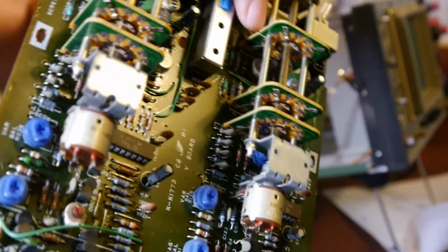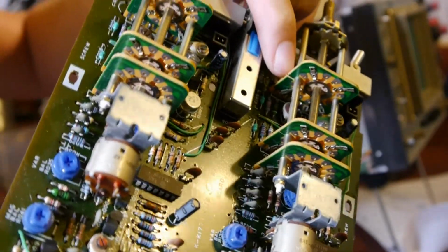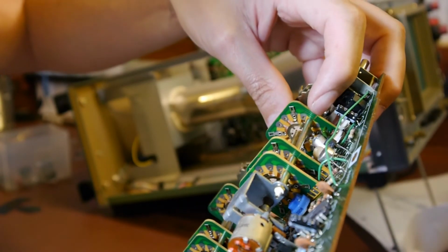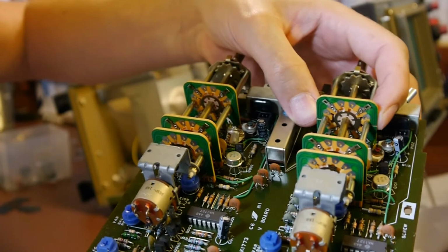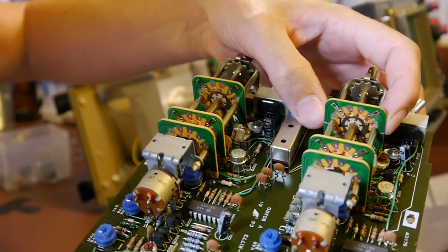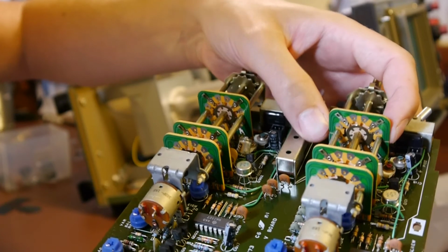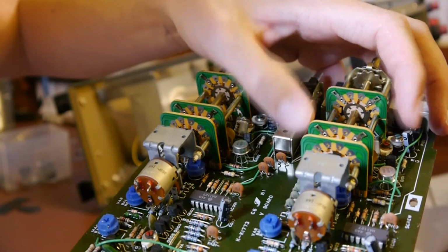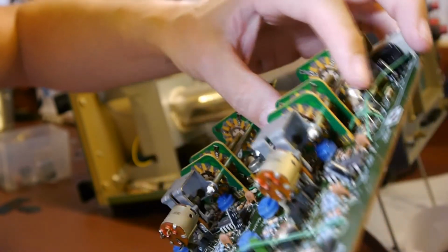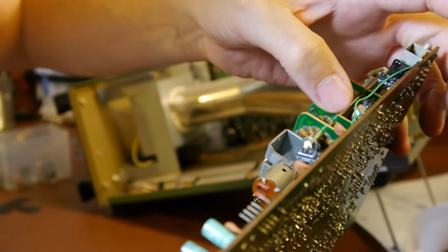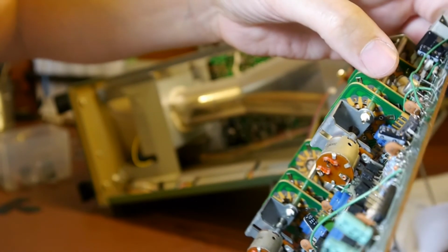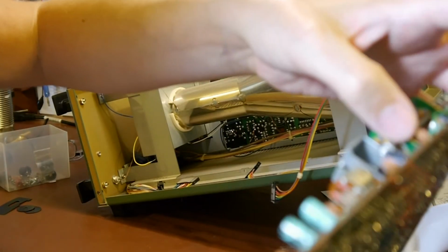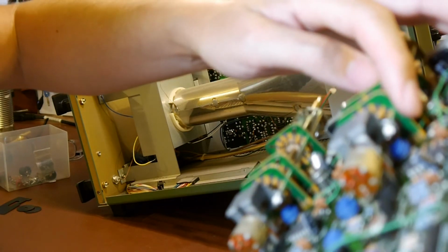You see it's cracked all the way across, straight through to that side. And it's not just that the circuit board is cracked, there are traces running up there, and all those traces have broken. This one similarly has a crack in it, and again it's broken all the tracks. That side is cracked and it's broken all the tracks. This board here doesn't look to be cracked.